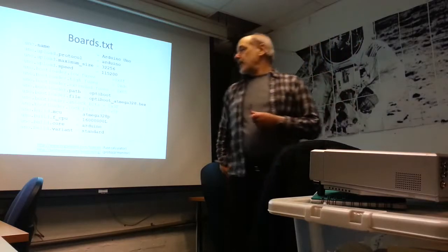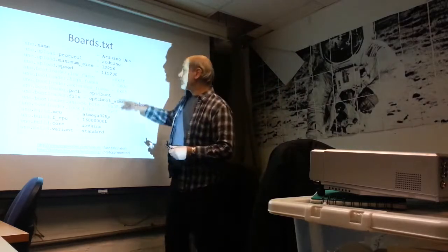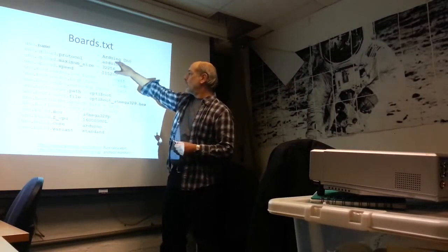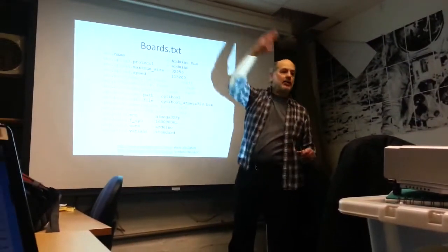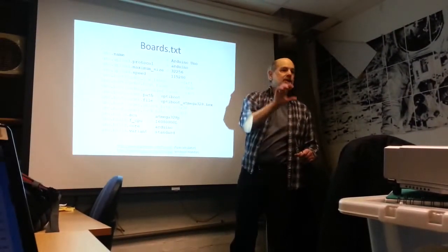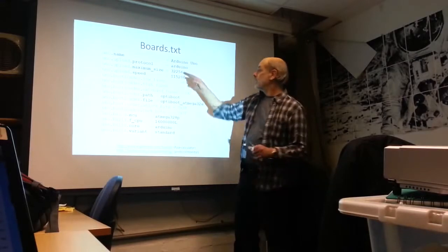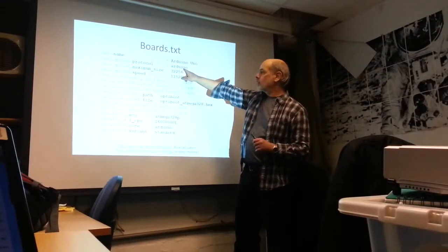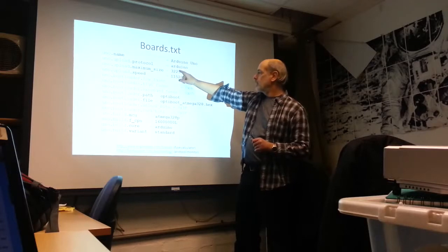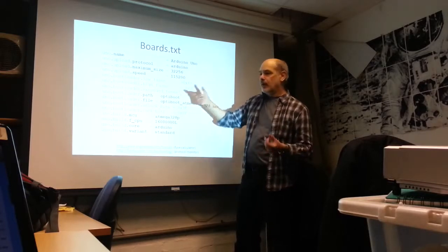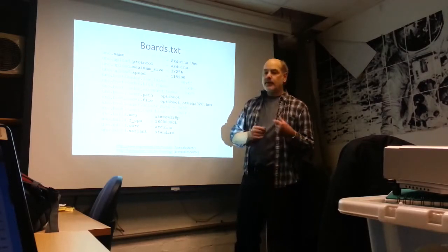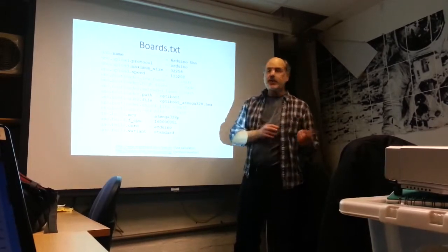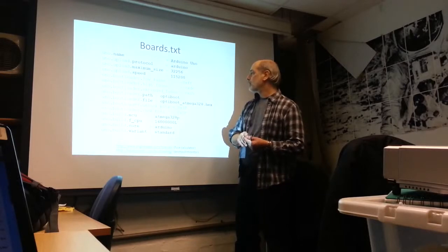Basically, it is the configuration for the bootloader. It has the name of the chip that you're uploading, and these are the names that the Arduino development environment puts in the list when you go to look at a board. It's reading them from boards.txt. It has the upload protocol that the bootloader is using, which for most of the standard boards is called Arduino, which is a slightly modified version of a standard Atmel protocol.